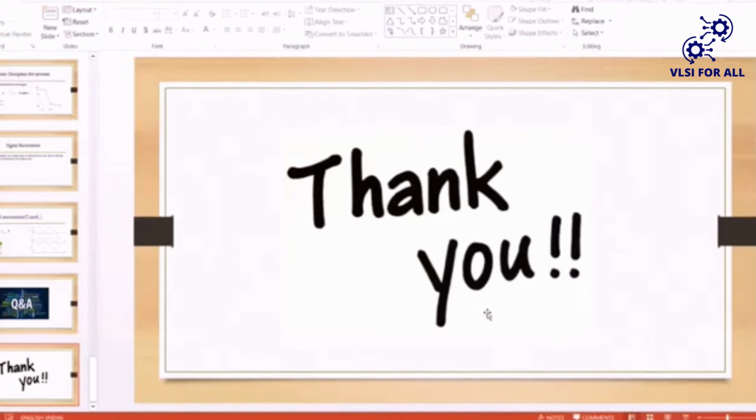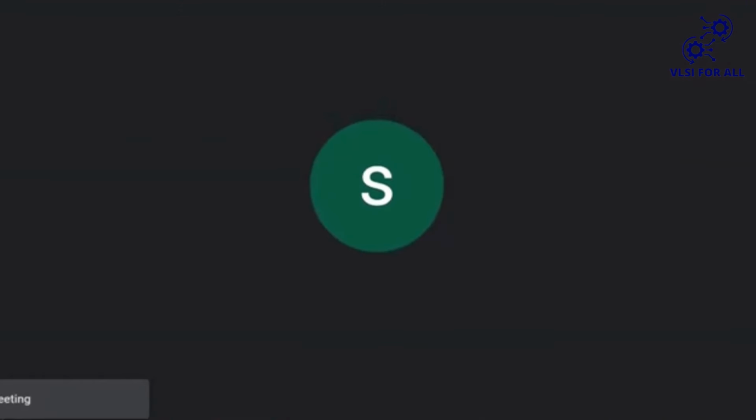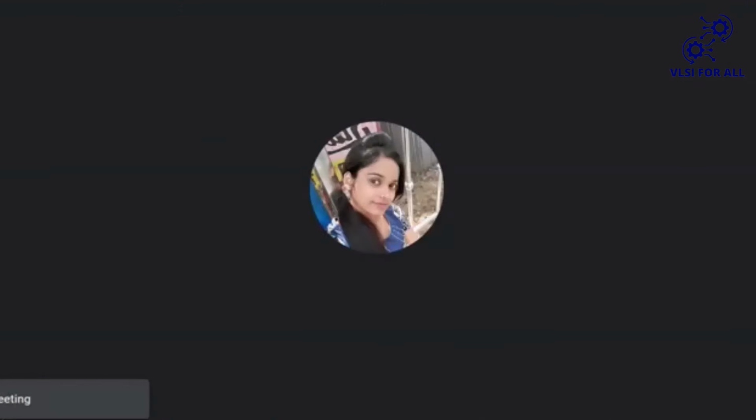See, to import the RTL code, you use read_hdl, and if you want to generate it, it is write_hdl only. And if you want to import the floor plan DEF, it could be something like read_def, that particular design DEF. It starts with read only, and I don't know exactly. Okay, okay, sir. So that is in terms of read only, I'm sure.